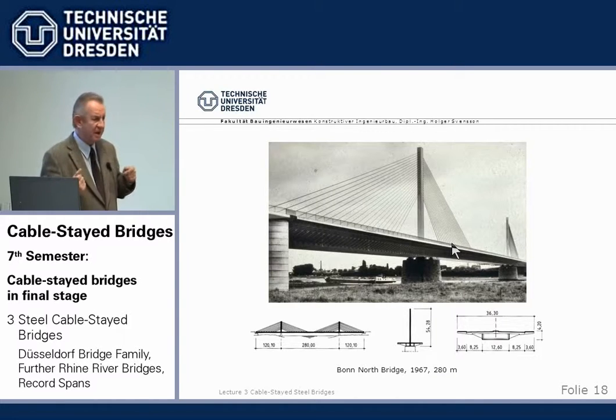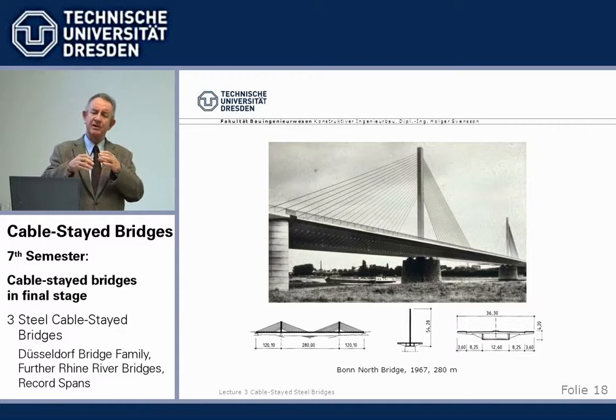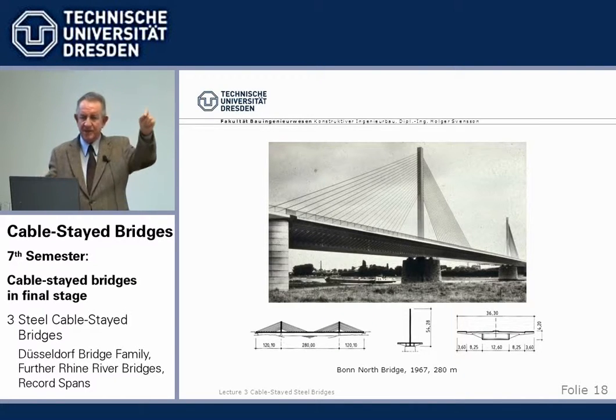Very important advantages. First of all, you can just use simple single lock coil ropes, 100, 120, 150 millimeter diameter, but you can anchor them easily at the tower and at the beam, and you install units at the distance of the cable anchorages. 4.5 meter cable distance, so the slices of the cross-section also have a length of 4.5 meters.